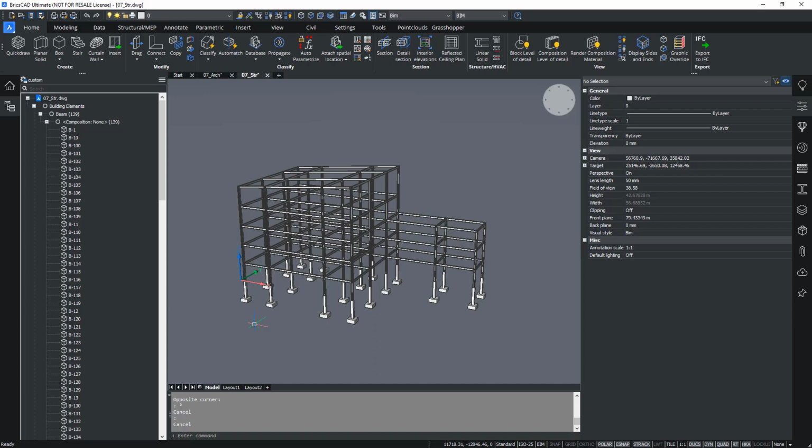Finally, in a BIM model, it's important to make spaces. With spaces, you can calculate floor areas, wall area, perimeter, volumes of spaces, etc. This is convenient to quickly calculate the amount of flooring, paint, skirting board, and ventilation flow that is needed to equip these spaces. On top of that, you can add properties to each space, such as their number for fire safety plans, or the type of coverings, and maybe whether they're handicapped accessible or not.